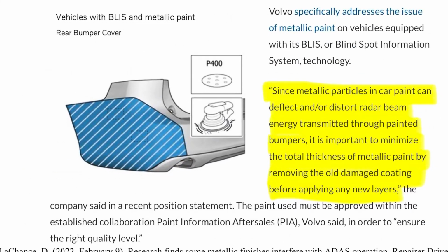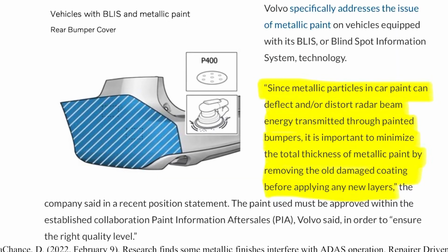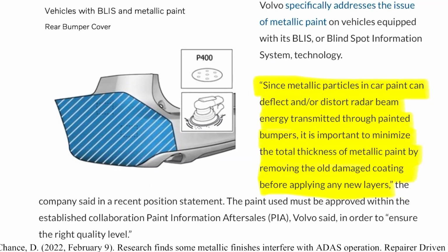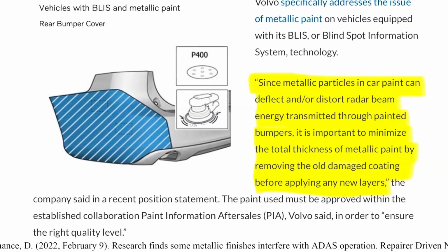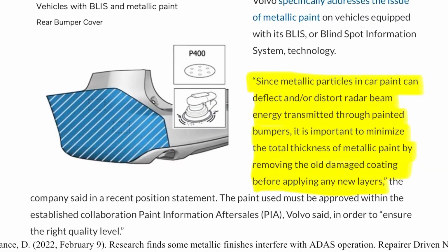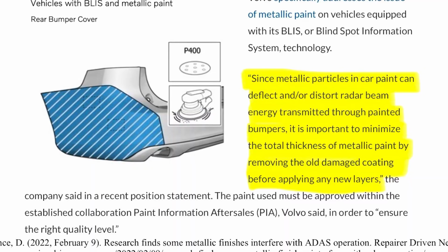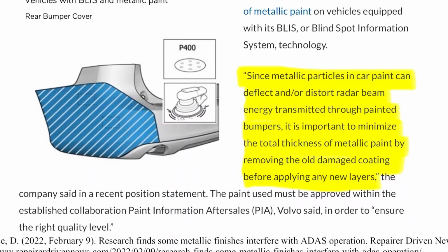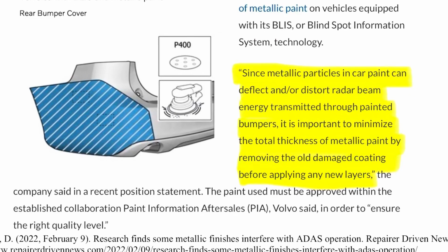Other manufacturers note that certain products in the paint, such as metallic pigments, can also affect the way the sensors read, and therefore this also goes into the concern of mil thickness. Other manufacturers may not allow any additional paint jobs to be performed over top of the bumpers, or in some cases, parking sensors that need to be painted as well. Always refer back to the OEM procedures and consider any potential concerns, especially regarding safety regarding paint film thickness.